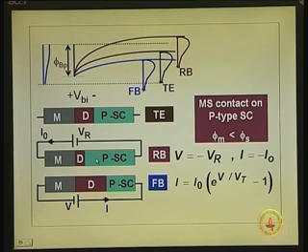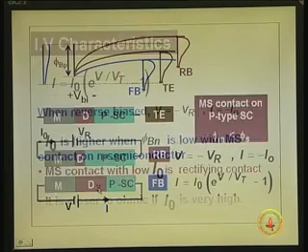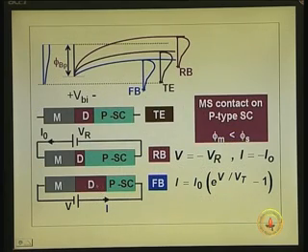There is a small problem here. I have just shown the depletion layer here, okay. This depletion layer actually should be wider. In fact, I just copied from there. Here you see thermal equilibrium, forward bias depletion layer decreases, reverse bias increases. So, actually here it should be the same way. In the reverse bias, the depletion layer should increase. So, this should have been there, we have to correct it, okay.